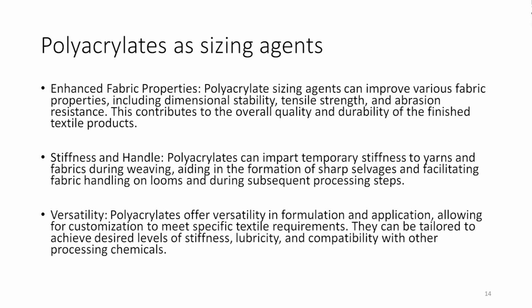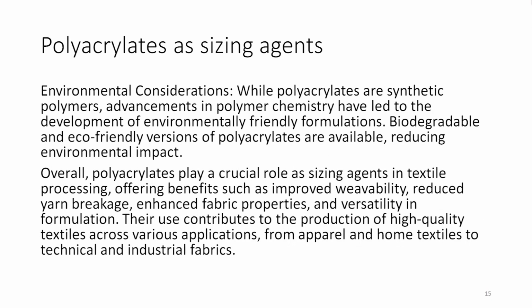Versatility. Polyacrylates offer versatility in formulation and application, allowing customization to meet specific textile requirements. They can be tailored to achieve desired levels of stiffness, lubricity and compatibility with other processing chemicals. Environmental consideration. While polyacrylates are synthetic polymers, advancements in polymer chemistry have led to the development of environmentally friendly formulations. Biodegradable and eco-friendly versions of polyacrylates are available, reducing environmental impact.